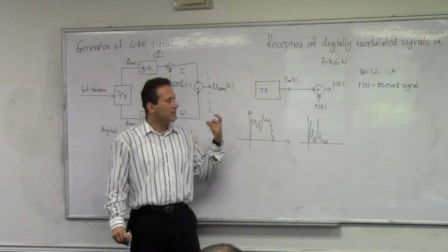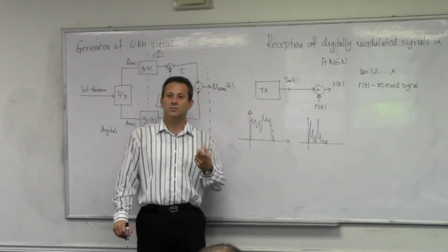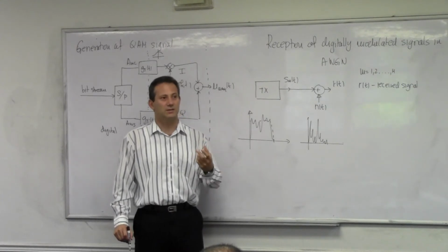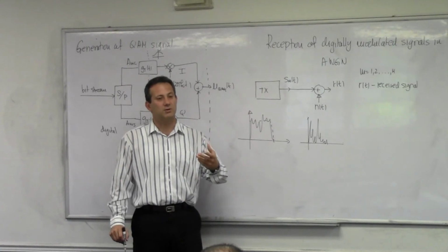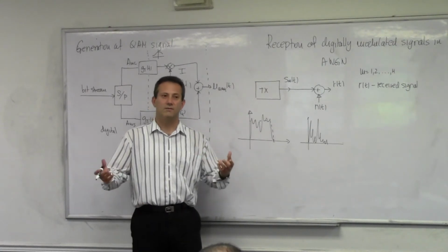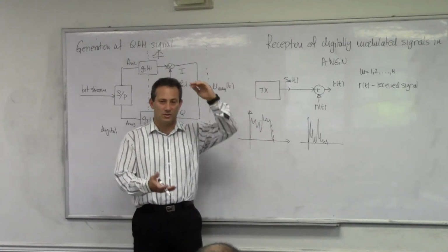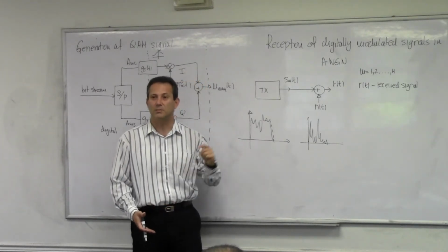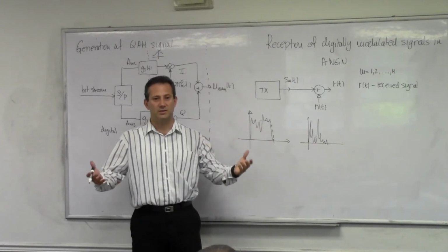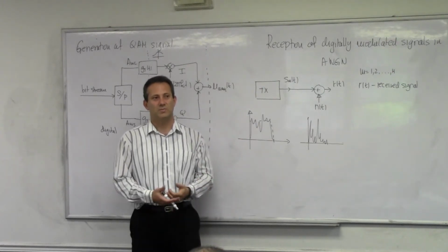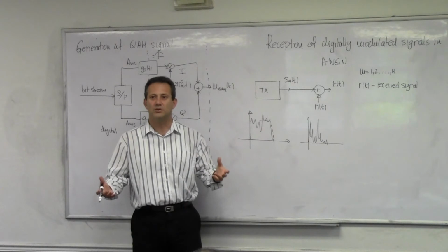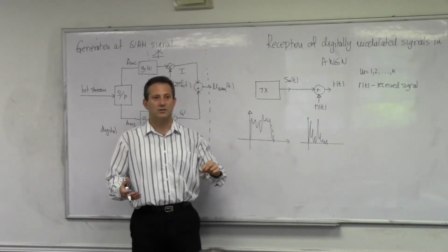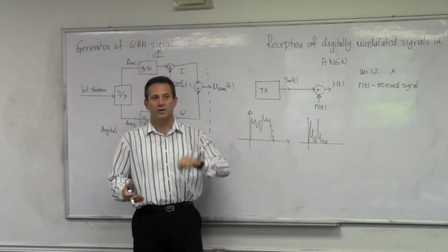So that's why, generally speaking, digital modulation is way more robust. Your transmitter doesn't have much control first. It has to convey all the information through a limited number of waveforms, a limited number of symbols, and then the receiver knows what to expect. It expects one of m possible symbols, and the decision here is: don't really reconstruct the symbol, try to decide what has been sent.